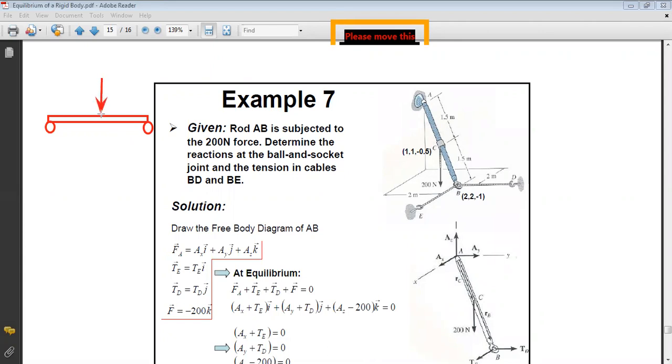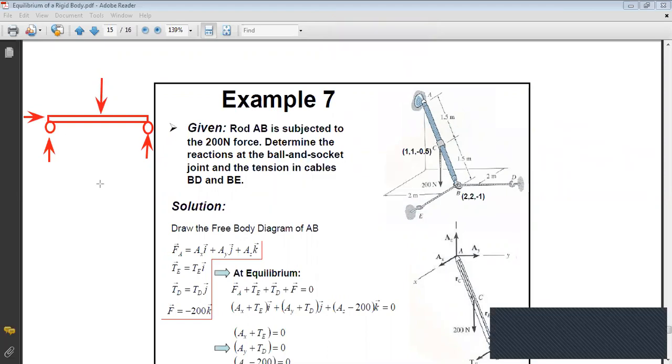I can have equilibrium, but not in all cases. So here, for example, if I just put a load in Y, I can have equilibrium because the 2 rollers can resist this force. But if I give you a problem with an X component, then you will tell me it is impossible to have equilibrium. So always when you have the number of reactions less than the number of equations, you should study if it is possible to have equilibrium or not. So this is an example here, okay?